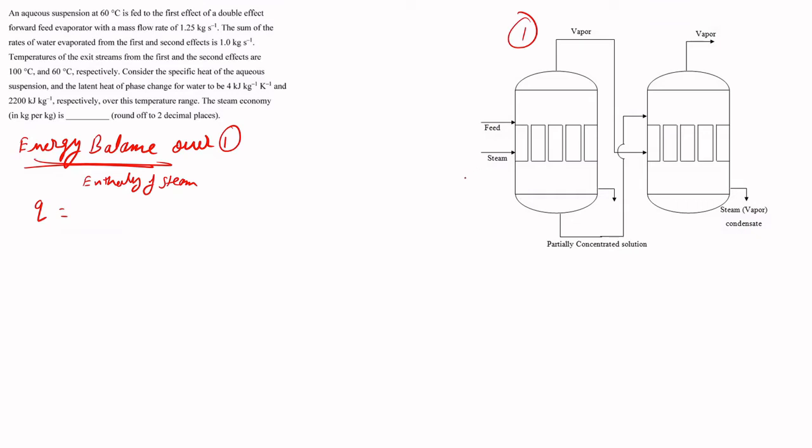So the mass flow rate was m dot s. So we can write it as m dot s into lambda s is equal to this. Basically, the steam will be used to change the temperature of the feed. Okay, so basically this will be liquid, and if this is F, this is L1, V1, V2, and L2. So the temperature of this liquid stream F will be changed.